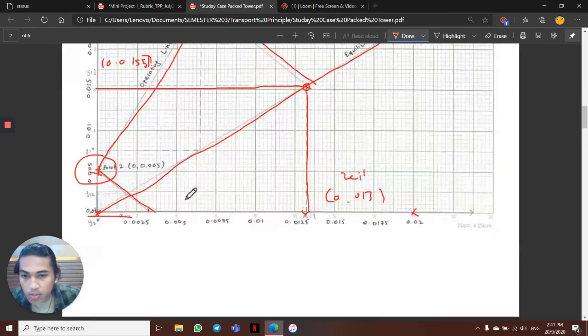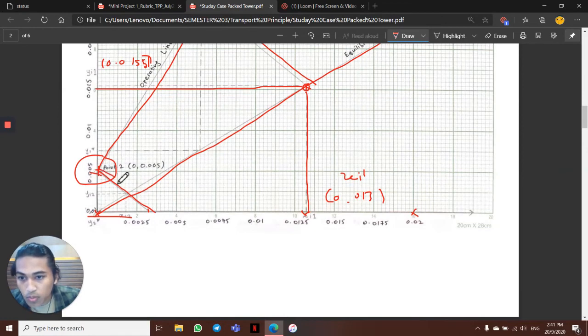Let me zoom. If you see here, this is the slope, and touching the equilibrium line, just from the intersection, pull vertically down to the x-axis. This is the value of xi2, and from the intersection, if you pull left horizontally, we will get yi2.